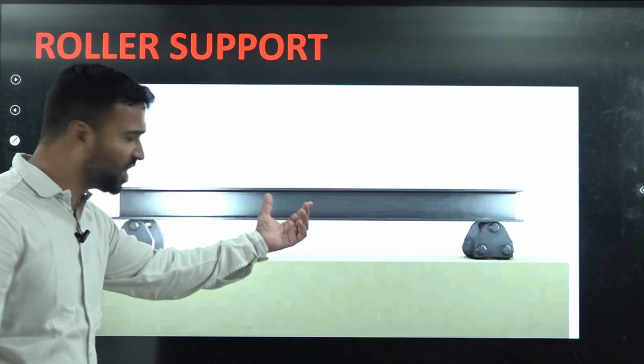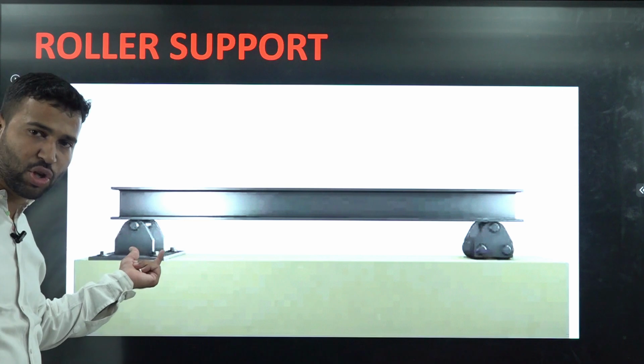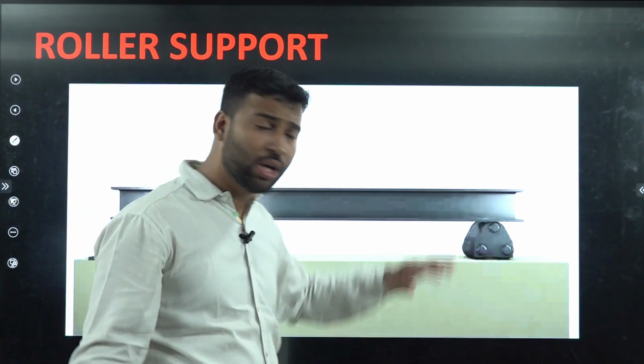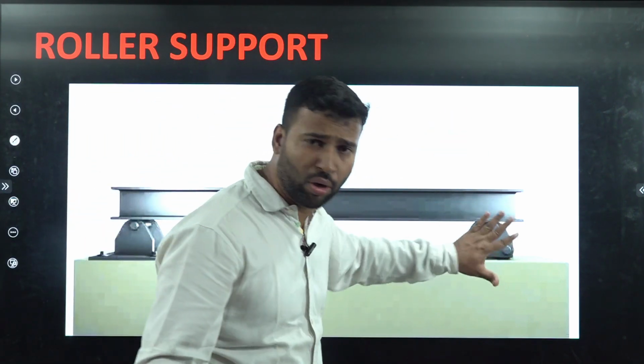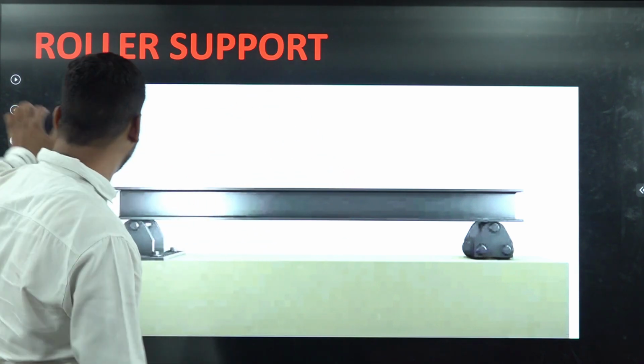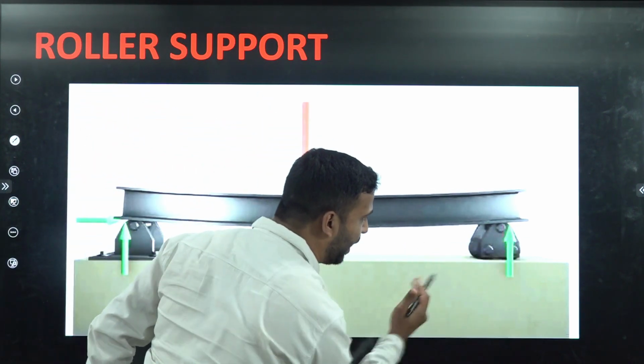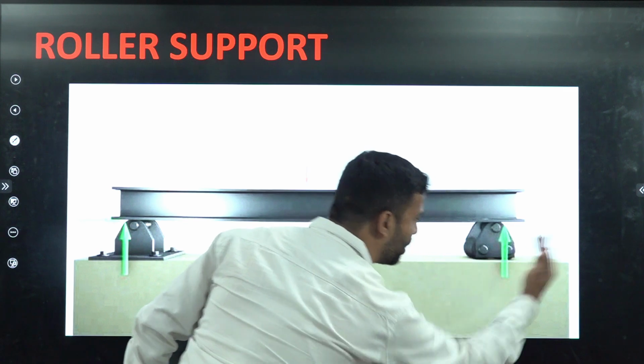Now moving towards the next support, that is the roller support. Again we have the same beam which will rest over one support in the form of hinge support, and the other support is roller support. Now you have to see this support only. Okay, I am again going to apply a vertical loading here. Just see the diagram. If we apply a vertical loading, it will rotate as well as it will move in the horizontal direction.